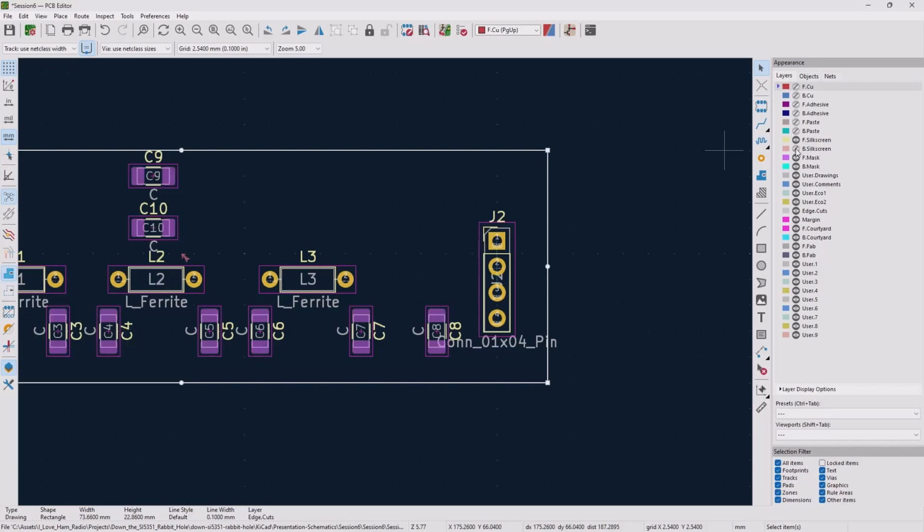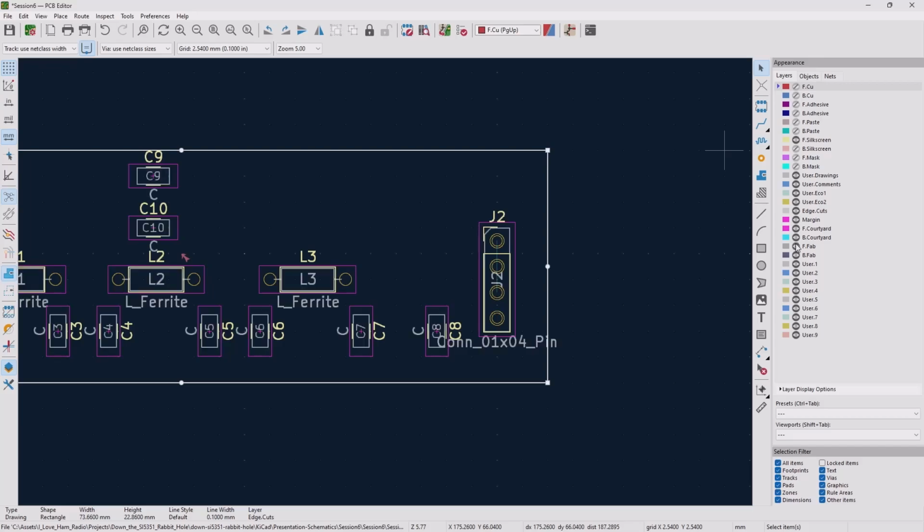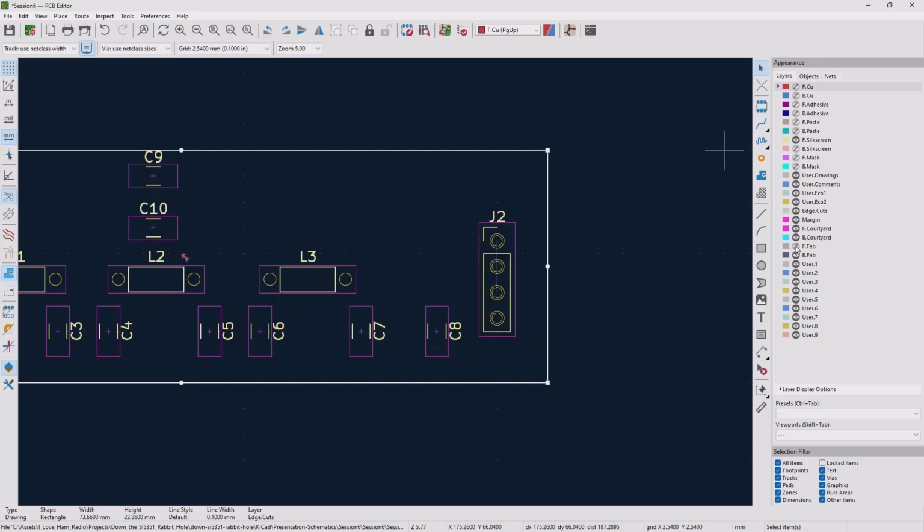So this is the front Silkscreen. You have to choose your Silkscreen for stuff you want to print. Let me turn off the background mask. Trying to figure out which one that is. It must be Fab. And that would be the values that you would send across, right? We won't send that to the fabricator, but we will send the front and the back mask.